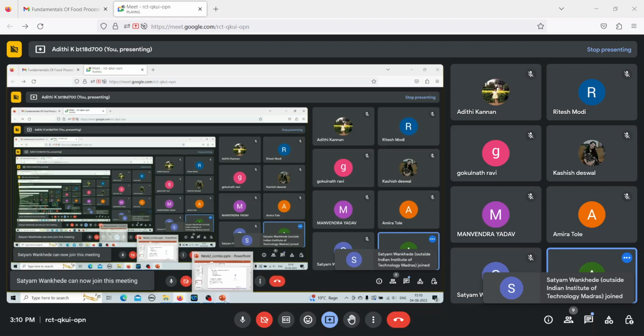If you have a long cylinder with extremely viscous fluid and you drop the ball on one end, the ball will not even fall. It will take a long time for the ball to pass from one position to another position. So a falling ball viscometer is not suitable for high viscosity fluids. It is in fact suitable for low viscosity fluids. So statement 1 is actually true. So we'll go to the second statement.